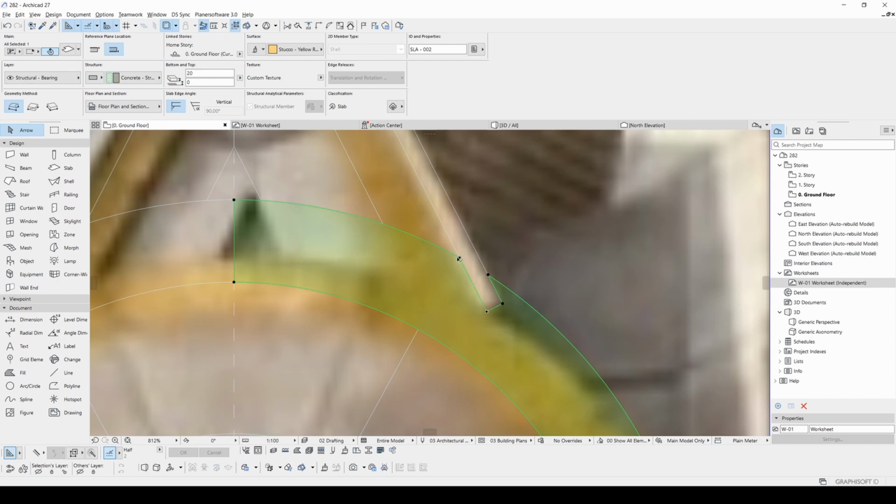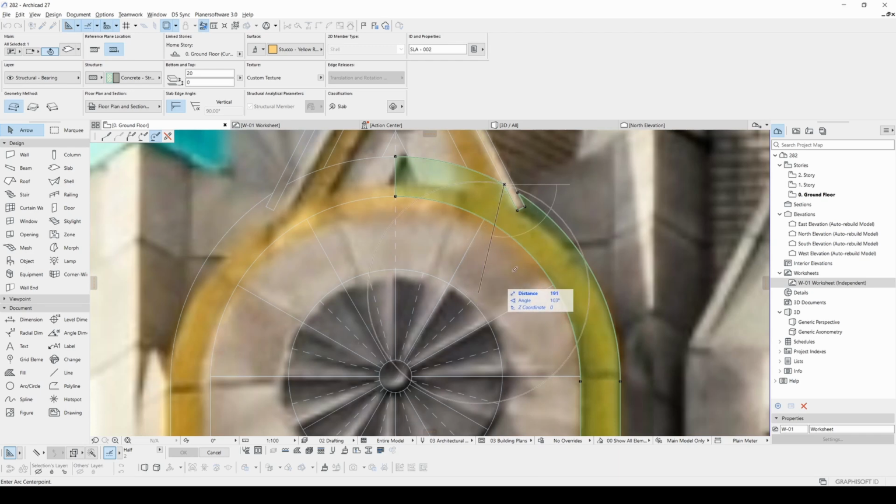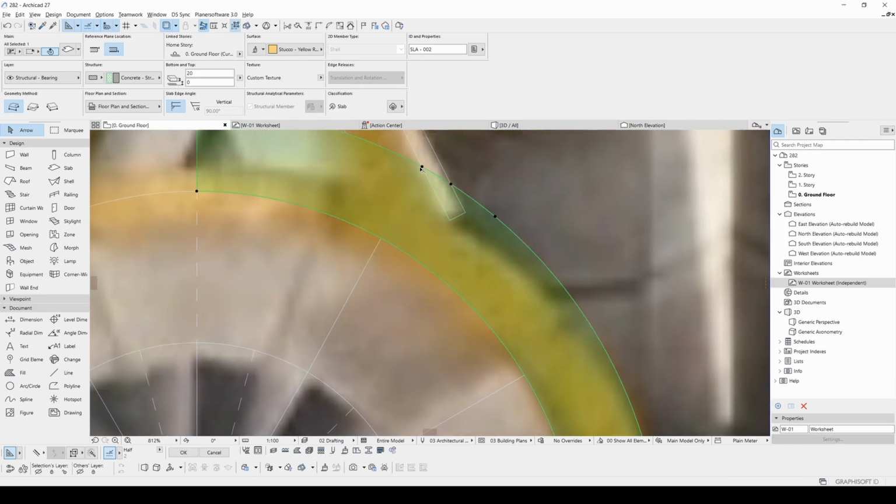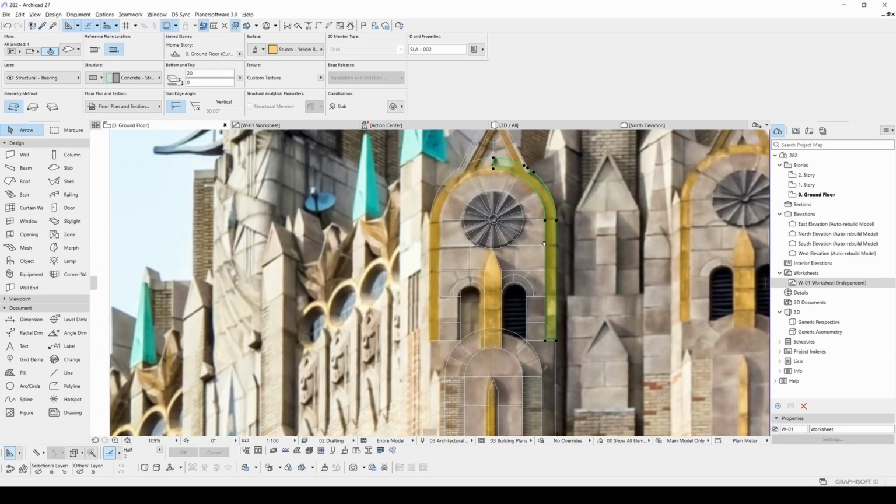Let's fill this gap. I'm going to hit this point, click this add polygon, and after that, let's click somewhere here. I'm going to determine arc by center point. The center point is here. And now I'm going to follow straight segment and close the shape. This is the first step.